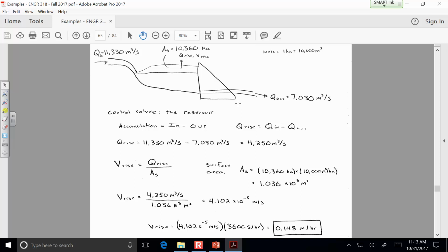So with the cross-sectional area, what I'm calling here the V rise, the velocity that the water is rising, even if the Q rise stays the same, the area could change. As the cross-sectional area that gets flooded increases, the velocity that it's rising goes down. That's commonly seen in situations like where the Mississippi River is flooding, or the Ohio River is flooding: the higher it gets, the speed that the water level rises decreases. So any questions related to this application of the continuity relationship?